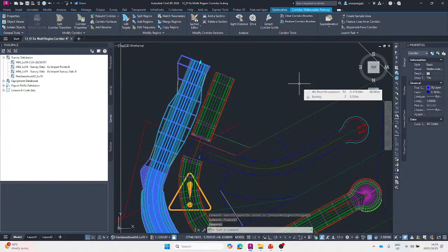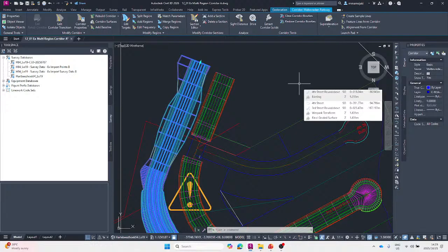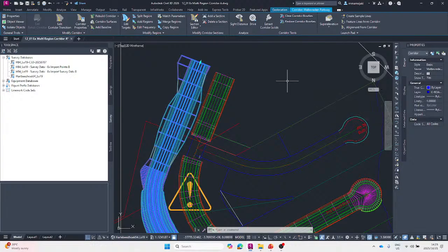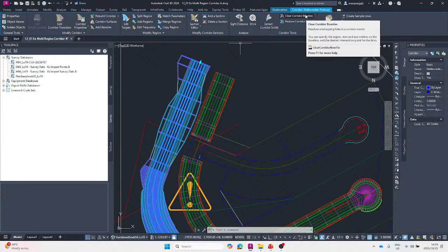And if I select just one single object within your model space, then that is when we will see our contextual ribbon tab, where it displays what you have selected, or editable information for that specific object that you have selected in your model. So at the moment, the contextual ribbon tab states that I have selected a corridor, and that is the name I have given the corridor.